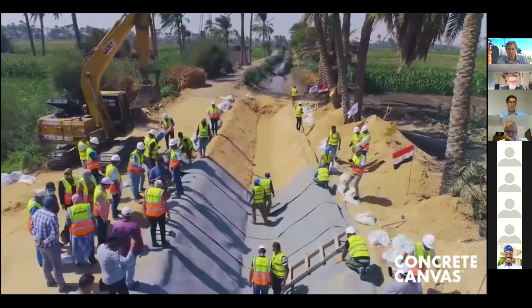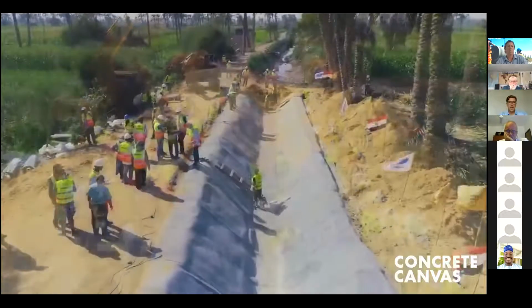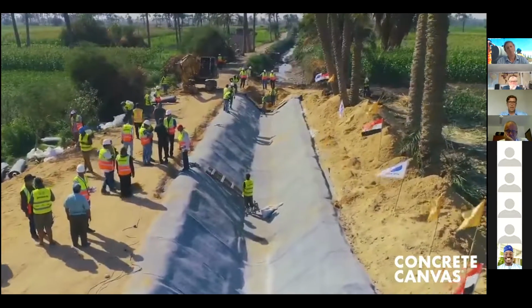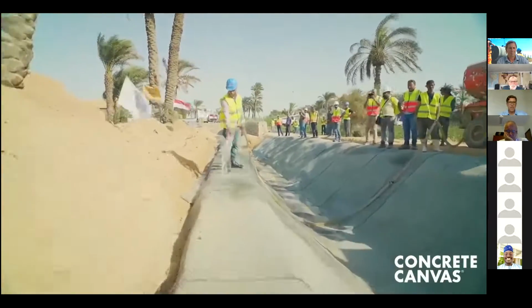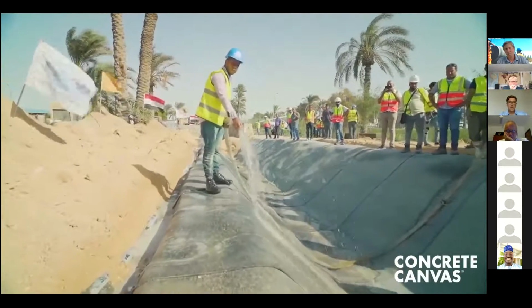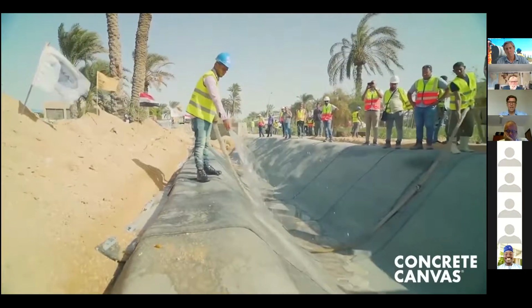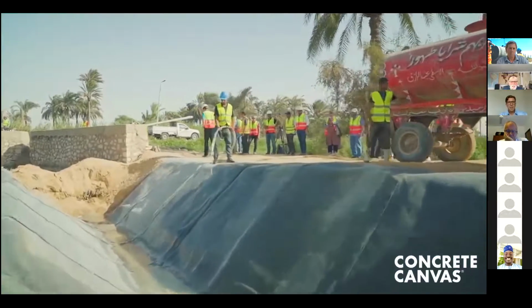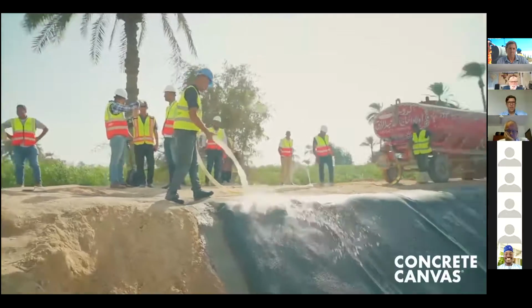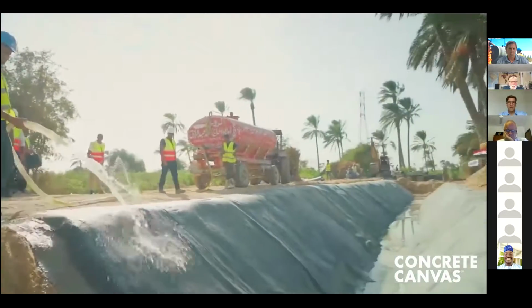Hydration was carried out at 15-minute intervals due to the high ambient temperatures, as well as the drying effect caused by wind. The material was hydrated 3 times at these 15-minute intervals to ensure saturation, and then a final hydration made at the end of the day's work. Upon completion of the initial 3 hydrations, the anchor trenches were backfilled and compacted by hand.